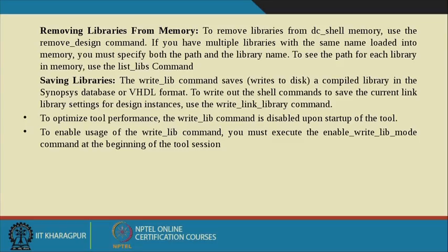So as I said, whenever I read a Verilog file, suppose my design file, into the Synopsys environment, it basically saves into memory. Okay. So how can I remove the libraries from that memory? Whenever you type list_libs, it will show you the libraries you have mentioned or are using for the current design. Now if you want to remove it, you type the command remove_design. remove_design will remove each and everything, that means whatever library you have mentioned and whatever design you have read will be removed from the Synopsys design compiler memory.